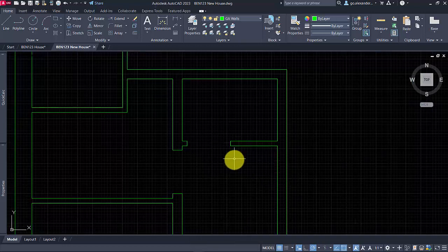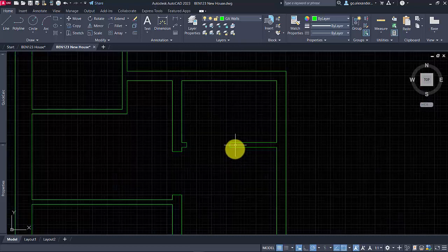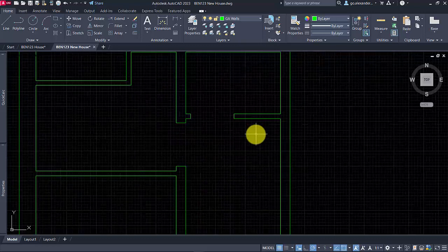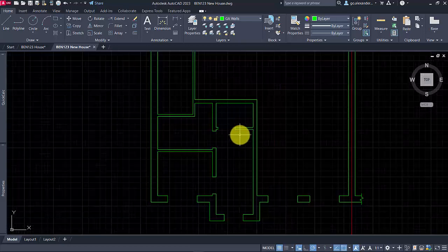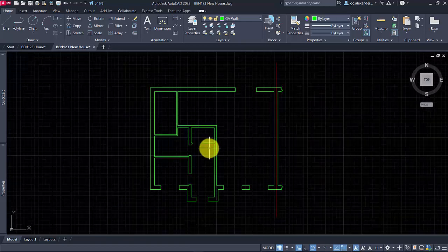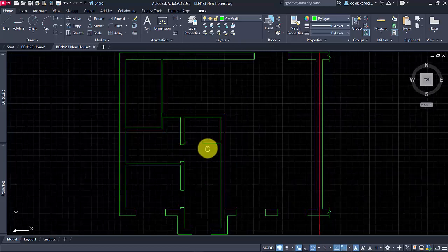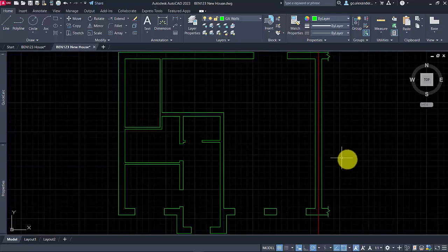There will be opportunity to put a light switch somewhere here, either on the stair carcassing, or if the stairs are an open stair as I would plan for my drawing, then that could go just on that part of the wall there. So yeah, continue with that process for the whole floor plan so that you have it complete.